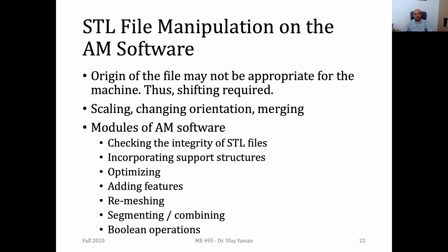You cannot actually remove triangles. If your CAM software is just working on the triangles, even though they have the same normal, you cannot eliminate them. But if you are doing a kind of direct slicing, as you know, we don't have any triangles there. Without dealing with such triangles, checking the integrity, you can do the slicing. But in STL files, you cannot remove.